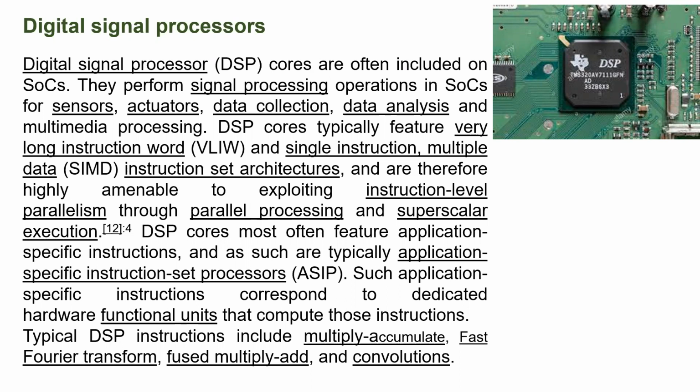The way logarithm converts complicated operations like multiplication and division into simple operations like addition and subtraction, in a similar way various types of transforms are used in digital signal processing to simplify the mathematical operations, and these Fourier transforms have to be done. Multiply accumulate operation has to be done. Fused multiply addition has to be done. There is one more complicated operation which is called convolution. This convolution is one main operation of digital signal processors. So convolutions are performed.